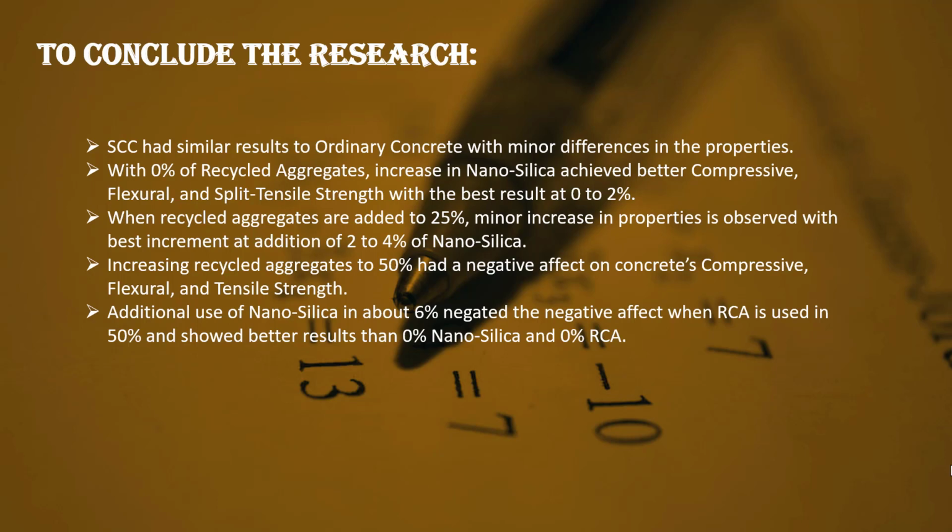Additional use of Nano-Silica in about 4% negated the negative effect when RCA is used in 50% and showed better results than 0% Nano-Silica and 0% RCA when it was increased to 6%.